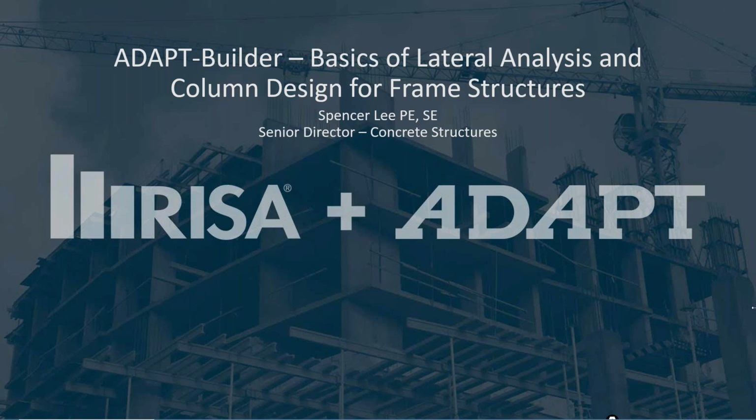We'll talk about combinations and load generation of wind and seismic loads. We're going to talk about load cases, how load cases are considered when we introduce them into a global or multi-level model in Adapt. We'll talk about usage cases, how we can assign stiffness modifiers for those usage cases, and then also P delta. This is going to be geometric P delta, introduce combinations relevant to that analysis.